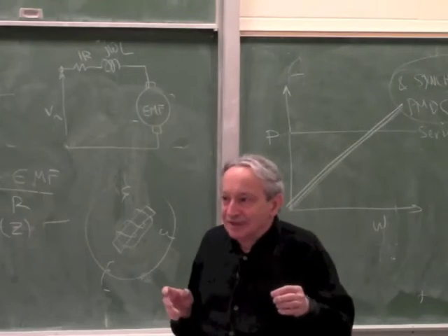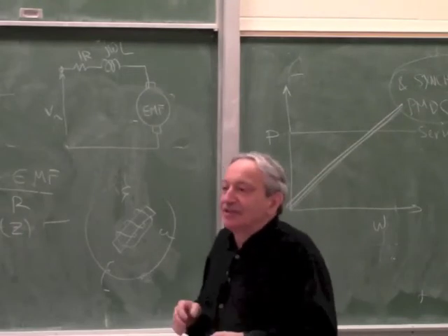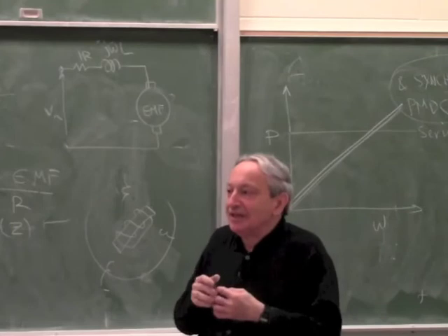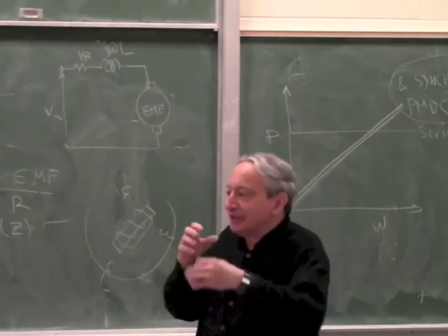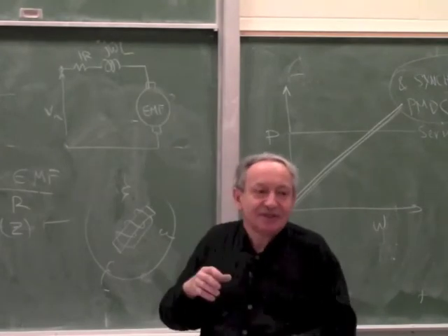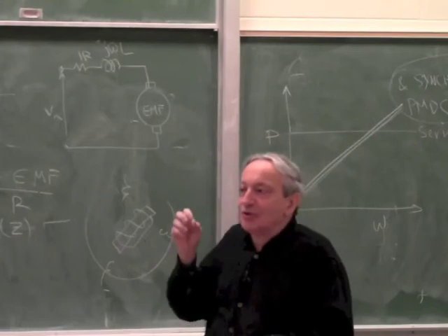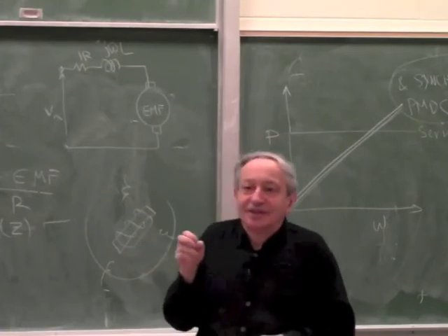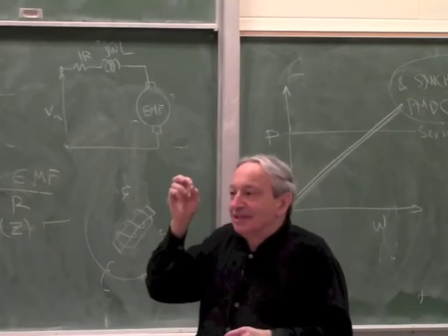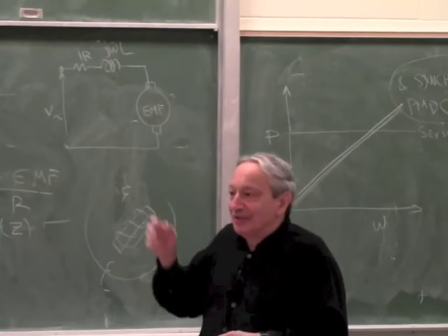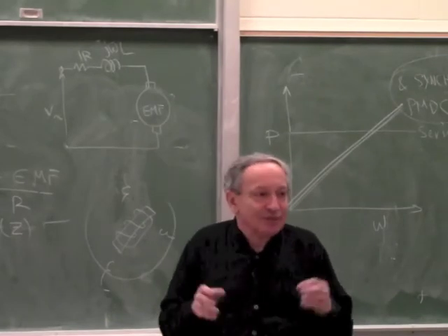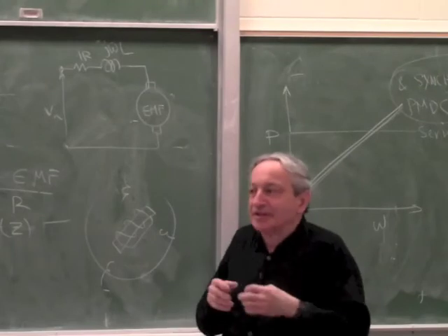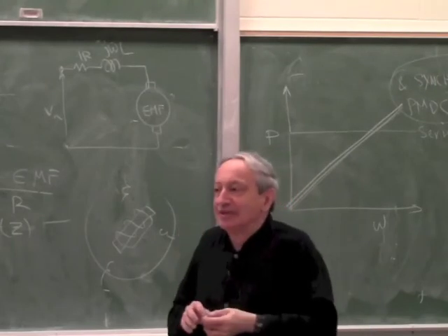RFI, right, it sends a lot of electrical interference, and it wears out, mechanically and from erosion. Mechanically it wears out just from wear on the brushes, but also it erodes, because each time you have a spark, it actually vaporizes a sub-micron amount of copper and graphite. So eventually the combination of the mechanical wear and the sparking will erode and needs maintenance.